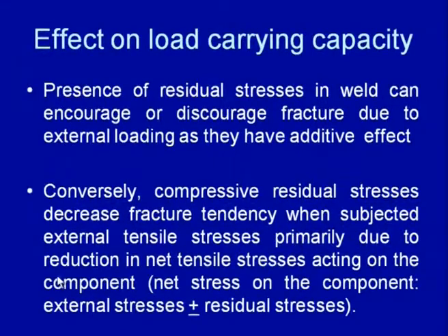primarily due to the reduction in net tensile stresses acting on the component, because the net stress on the component is obtained from the external stresses plus or minus the residual stresses. For example, if we are applying external stresses of tensile type, then the presence of compressive residual stresses will decrease the net stresses, while the presence of tensile residual stresses will increase the net stresses acting in the component. So, depending upon the nature of the external applied stresses, residual stresses can help or can deteriorate the mechanical load carrying capacity of the weld joint.